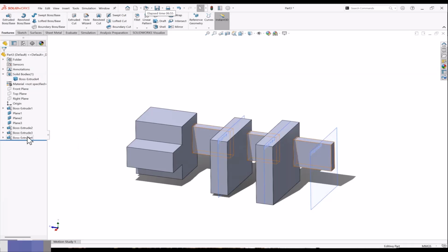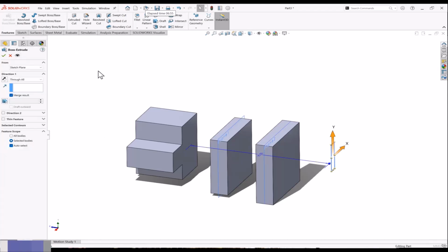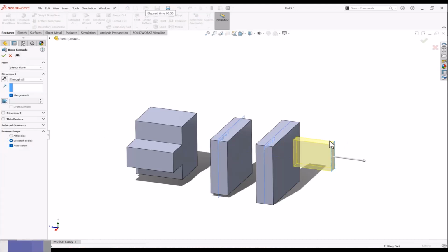Now let's see the next thing. So I have understood how I can extrude directly, right? There's one more way of extruding the part. You select the part and go to extrude. Suppose I don't want to extrude from here. The sketch is here, but I don't want to extrude from here. You have the From option. In the From method, by default it is on sketch plane. You can also tell it the face from where you want to start the extruding.